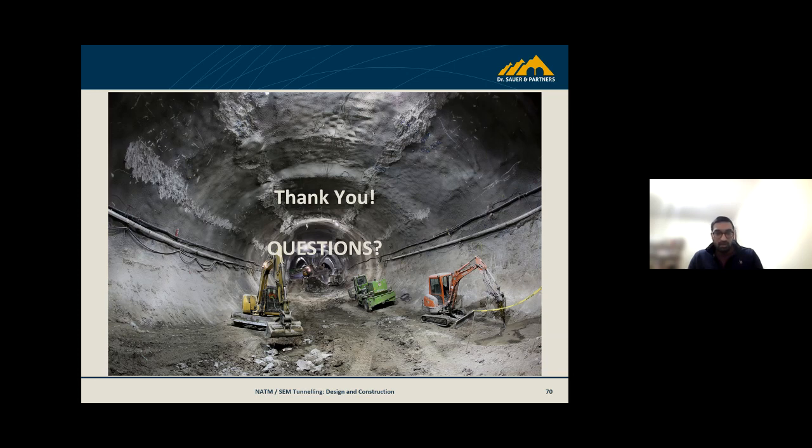So it's a well-known medium, and people have been advancing various techniques. But for the other side of it, the instrumentation and monitoring has definitely helped to identify problems early. Convergence, we've seen a lot of times in tunnels, indicating possible weaknesses or ground-related issues, which then we address, whether by changing advance lengths, doing more probing, or increasing dewatering efforts. That's definitely been the case in a few of the tunnels that we've driven in London, especially with the River Thames just above us.